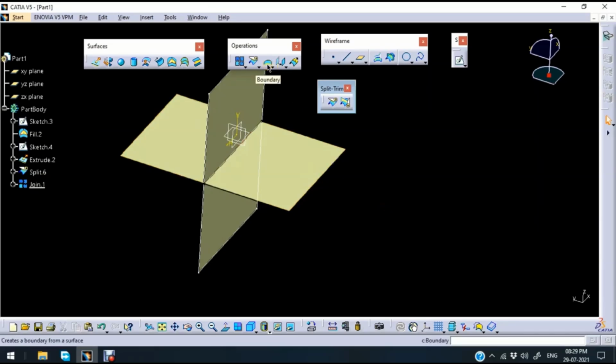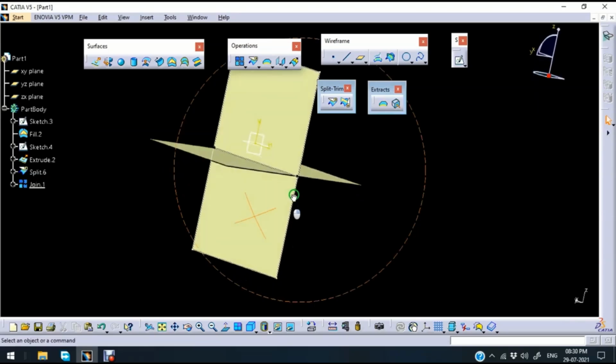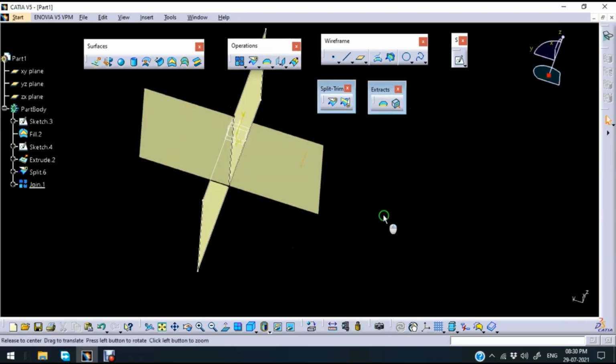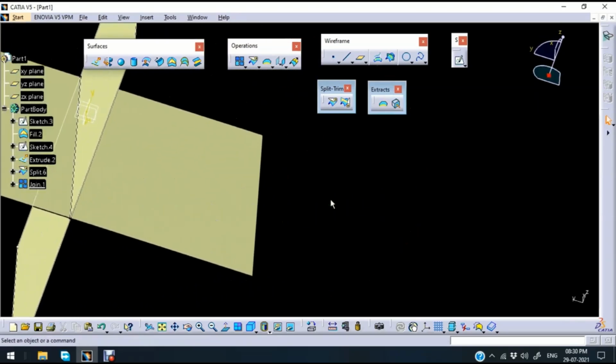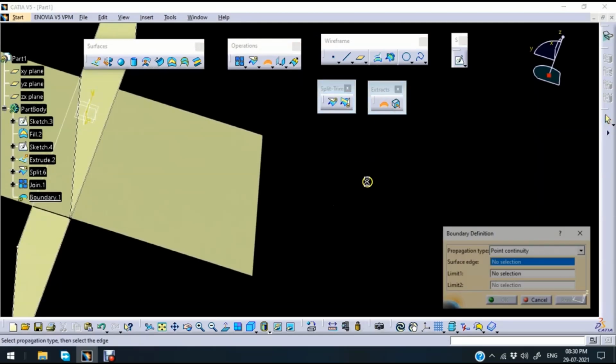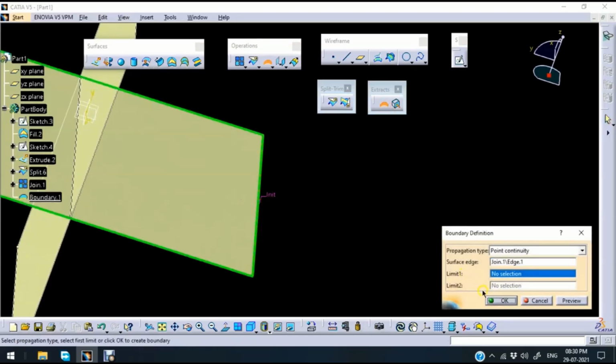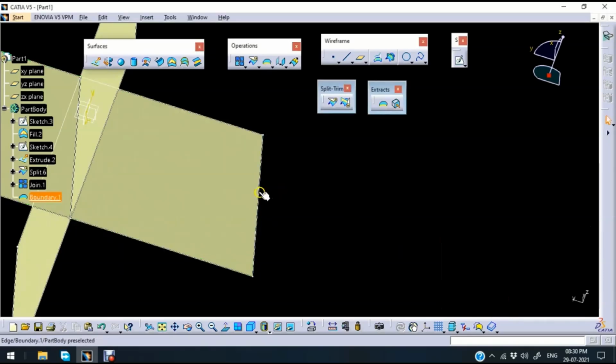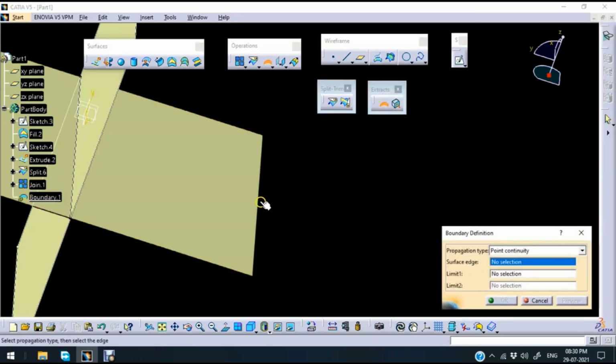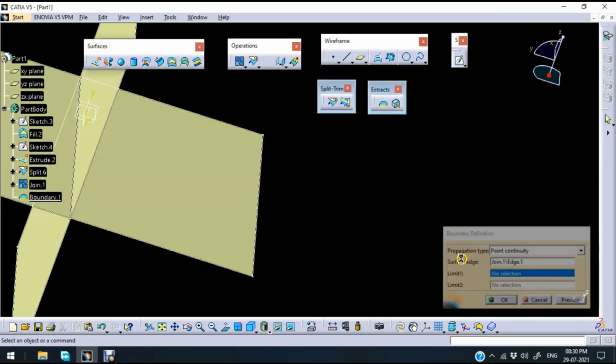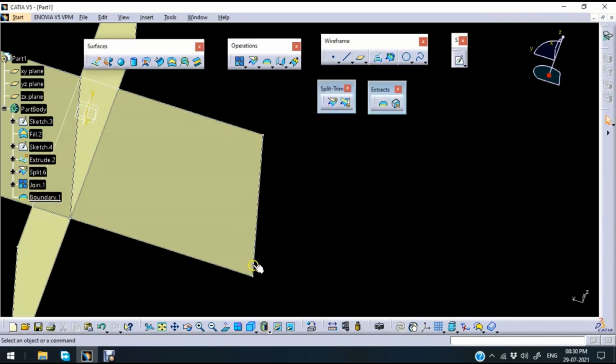Then the project tool. If we expand that, you can see two projections. For example, if you want to project any edge similar to a 3D element, project 3D element works. For example, select this corner. You can see now there is a line. Previously there was no line, so we will do control Z. Now there is no projection. If you use this project tool, I can project the line on these edges. You can see the edges are projected.